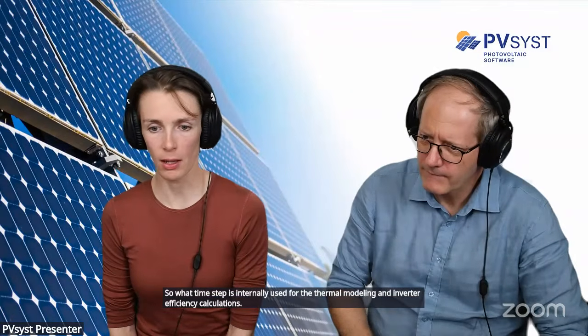Thank you. Then we have a bit more complex question about the simulation details. What time step is internally used for the thermal modeling and inverter efficiency calculations? And can this improved resolution better represent transient cloud events, inverter behavior, and PPC ramp rate response in utility-scale PV plants? Indeed, the time step in the simulation will be the same, and the internal models, also the thermal models, will use the time step that's in the simulation.